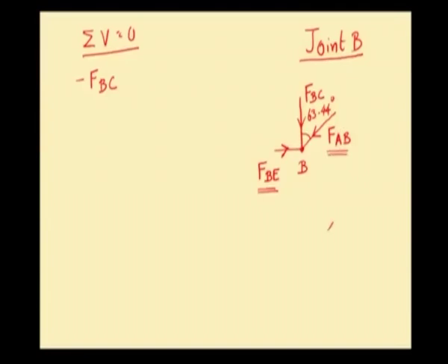FAB goes like this, that is it starts here and it ends up at joint B. So, this is our joint B. To travel along this particular path, horizontally we have to move towards left till this particular point and then vertically we have to come down. So, this is the horizontal component h of FAB and this is the vertical component of FAB.